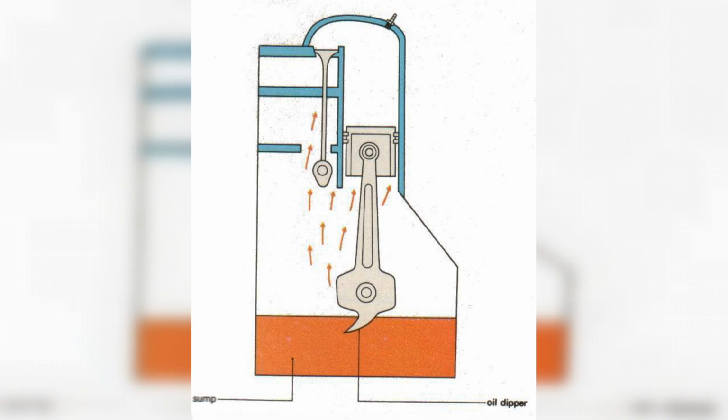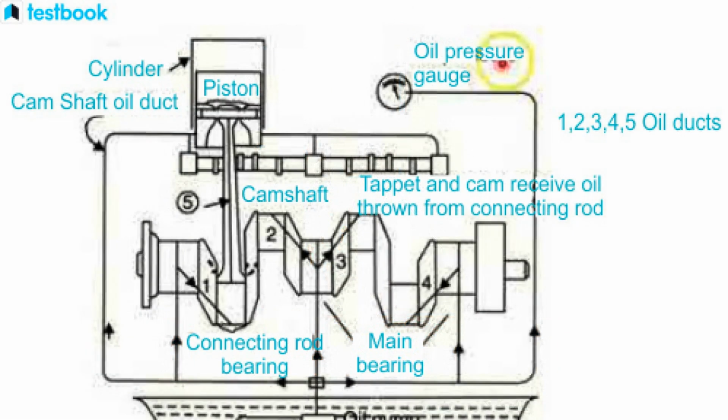In such systems, the oil does not go into the oil pan, but into a special tank located independently, and from here the pump pumps it into the main line. The main advantage of such a system is to ensure stable oil supply to the powertrain components on uneven road sections, downhill and uphill gradients, side rolls. In wet systems under such conditions there is oxygen starvation, especially if the rough road section is long, and there may be a leakage of lubricating fluid through the crankshaft oil seals. Dry crankcase systems have no such disadvantages.